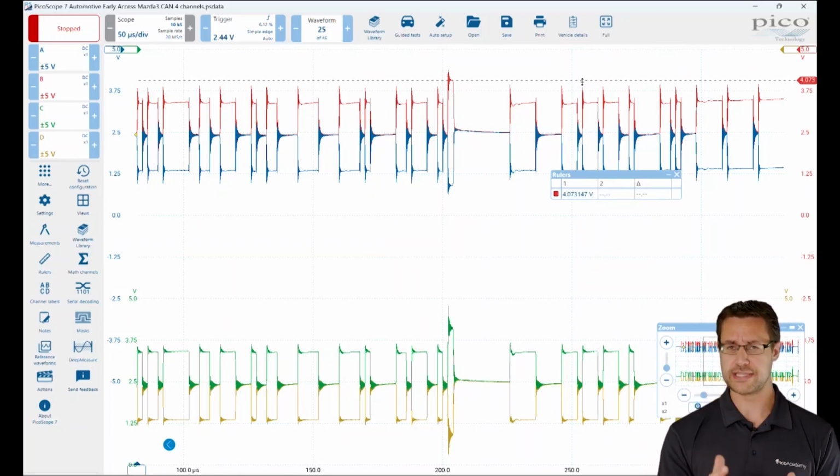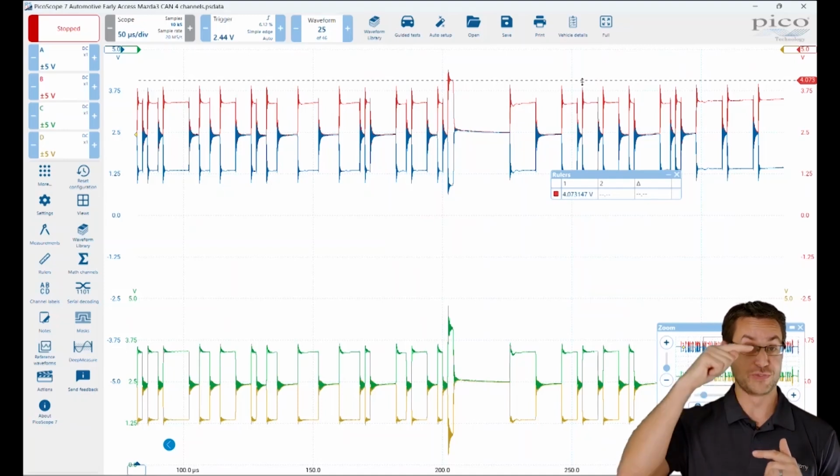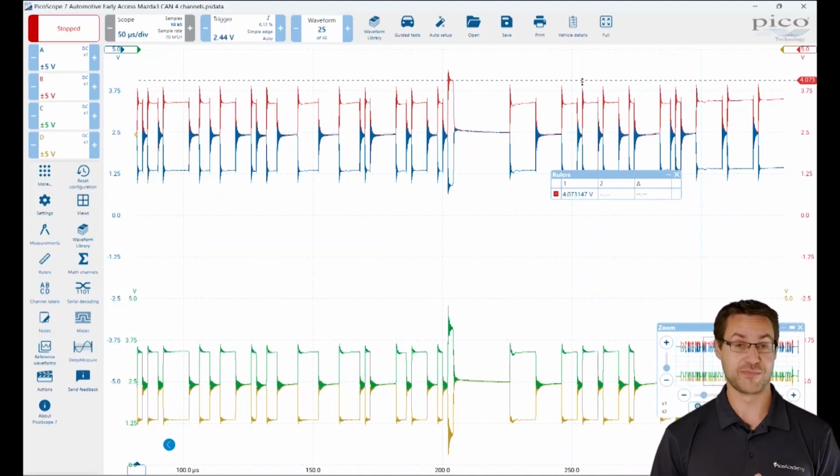Now, why is that? There is a terrific series on YouTube from a gentleman called Joe Bell. I do encourage people to go review this because I've learned a lot from these videos. He actually explains what's going on here and demonstrates how it's happening as well. So basically, as every ECU comes online, acknowledges that message, it's changing the resistance value of the network momentarily, and in doing so, forces the voltage to creep up ever so slightly.